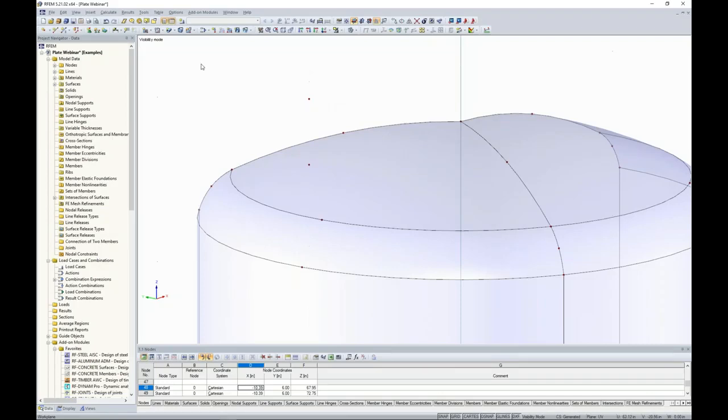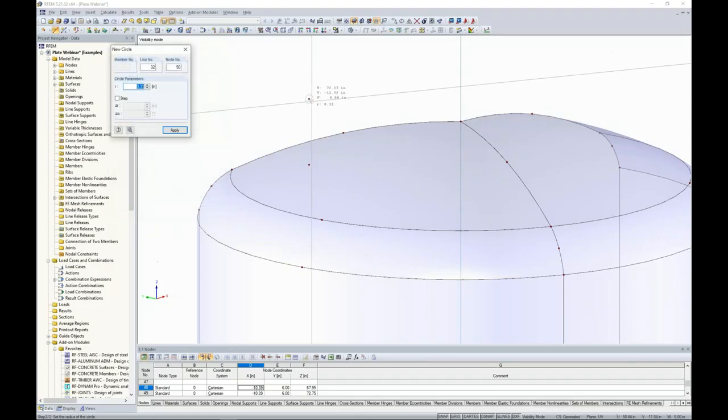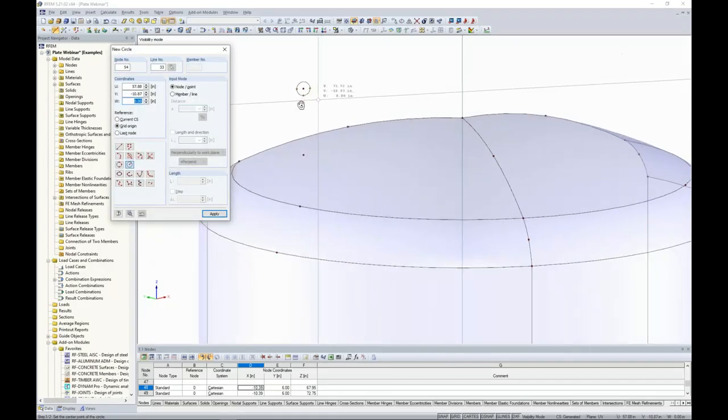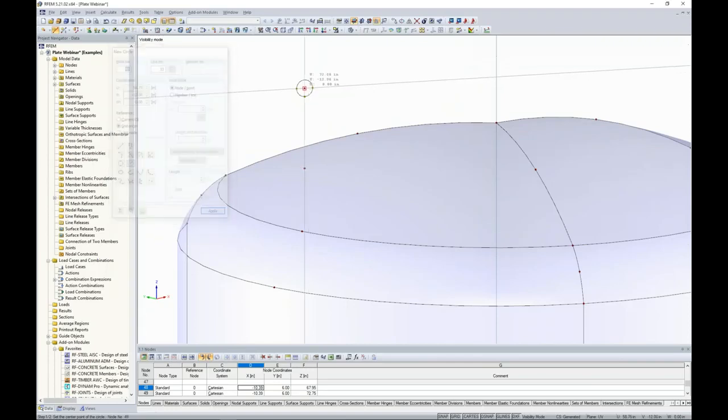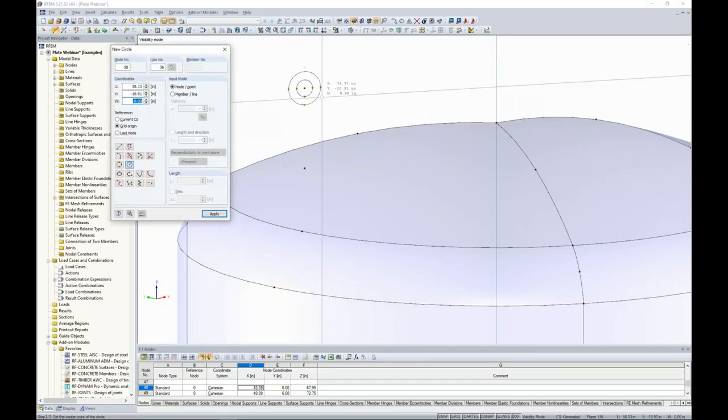And I just want to draw the circle as a line element. So we go up here to our line element, and in addition to straight lines and arcs, we also have the ability to define a circle with a radius. So I choose this option. I just simply snap on that center point. I can type on my keyboard the size of the radius as 0.5 inches. I hit enter on my keyboard, and now we have our first circle shown. I want to do the exact same thing with the outer circle, but this time the radius will be 1 inch. I hit enter on my keyboard.